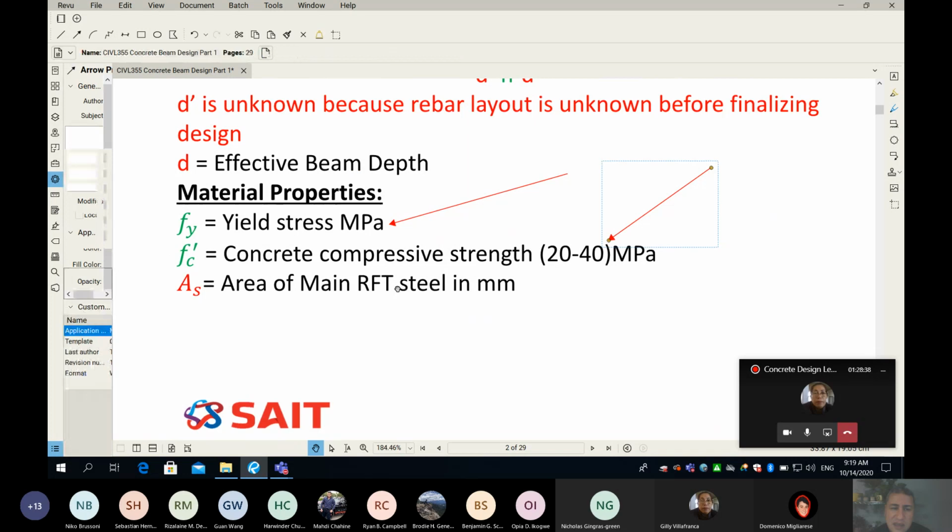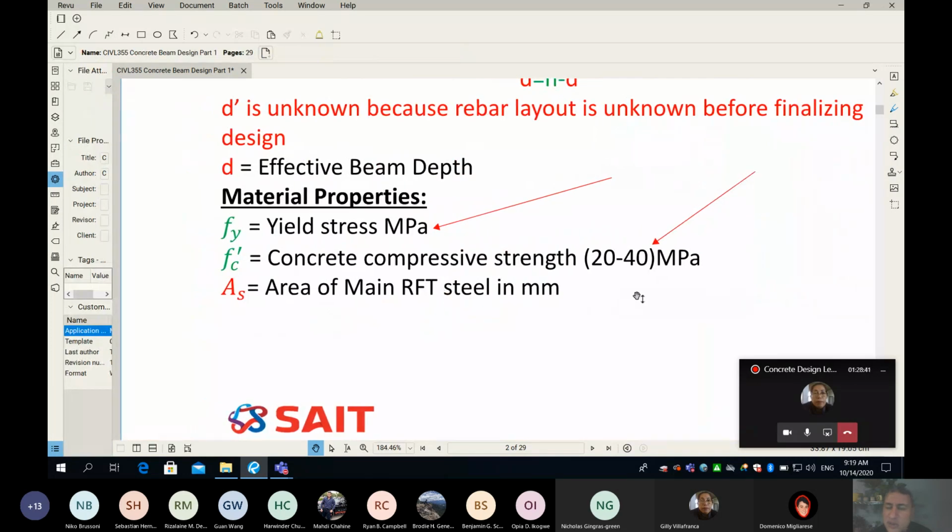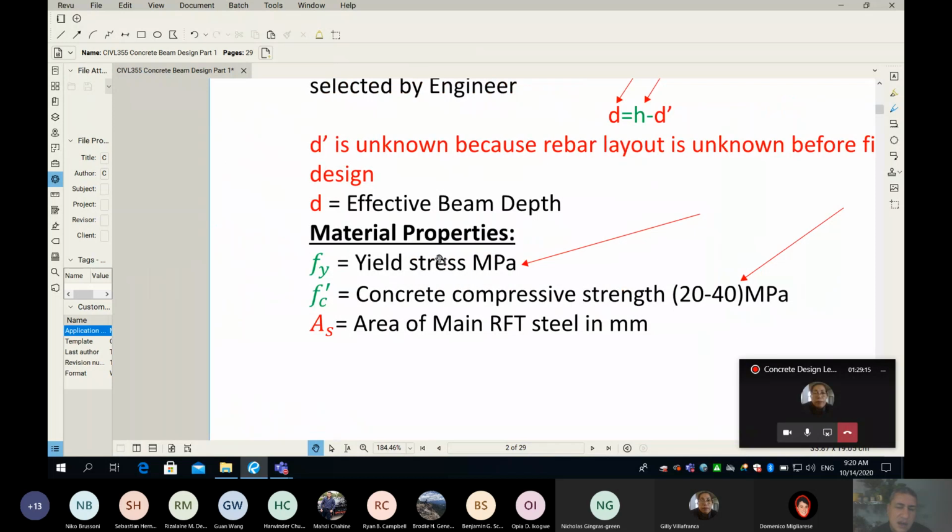So how do we handle this unknown? We just start from something reasonable. Typically beams are made of 25 MPa concrete, or maybe 30, and columns, because they have higher loads, we typically build from 34, 35, and 40. The way we do it is iteratively, which means we start from 25, and if it doesn't work, I can modify my design a little bit and change it to 30 and see what happens. Okay, and then finally, so far we have two red colors. Look at this, please.